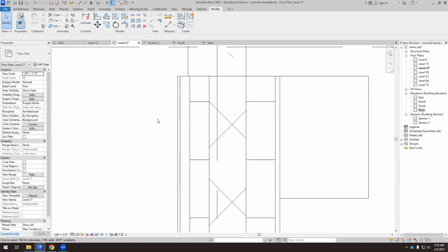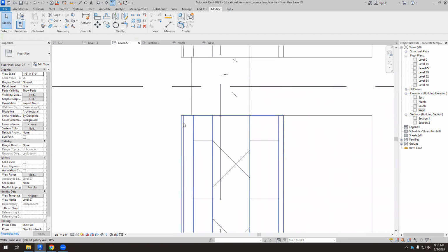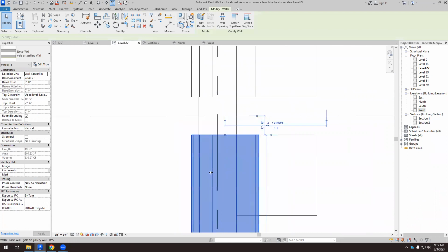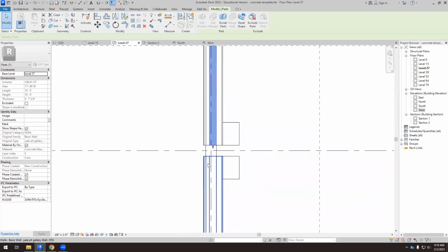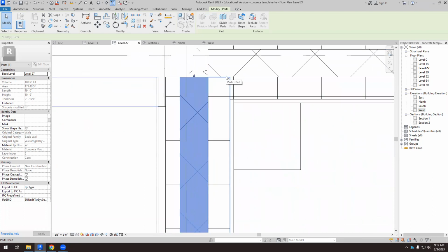Well, this can happen. So we can have a floating steel layer. It's impossible. So we have to fix that steel layer to the main structural element, and the main structural element here is this concrete masonry unit thing. So how can we do it?